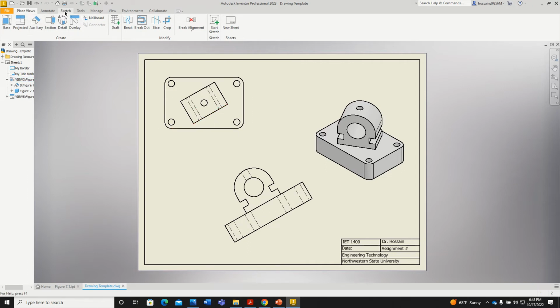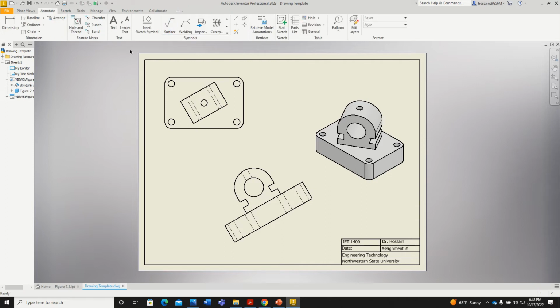Okay, so I'm going to add some annotation, which are the center marks. You need center marks here, here, here, here, and then you need the central lines. The central lines should be, you can use this one as a central line. So you should have a central line using this line over here and this red line over here that will be aligned with this circle.